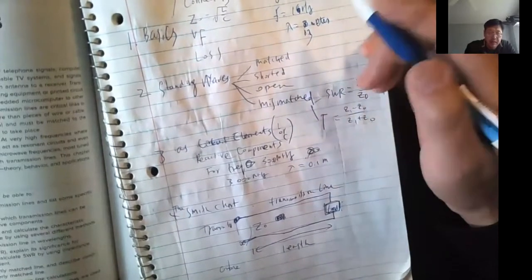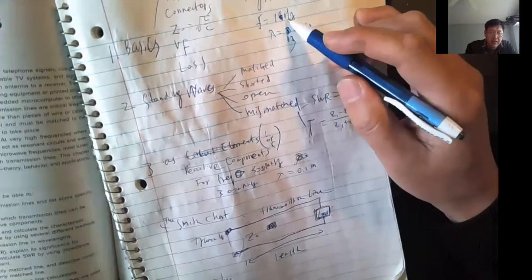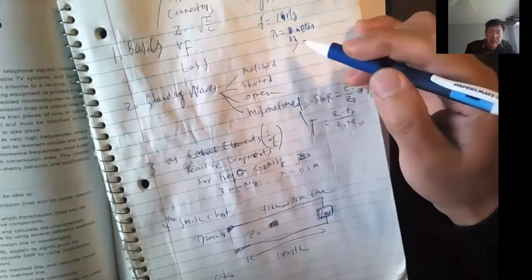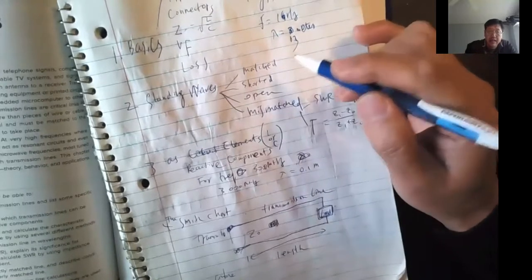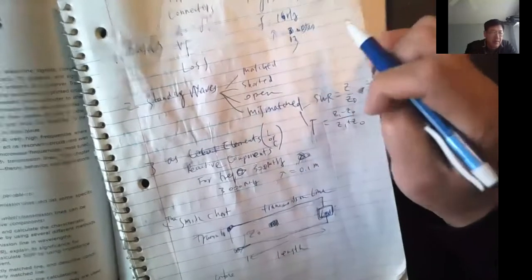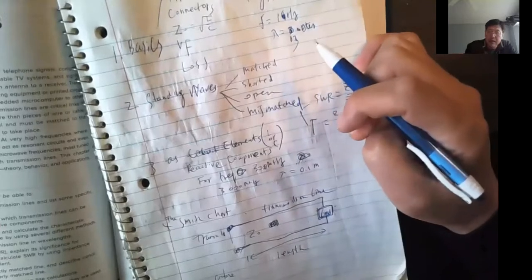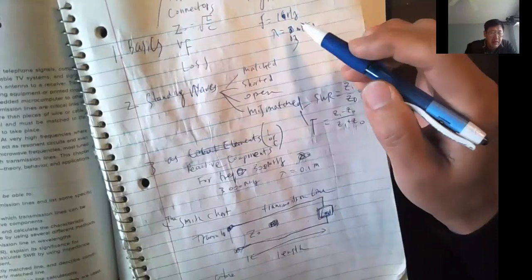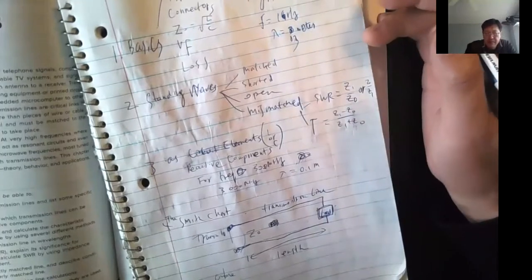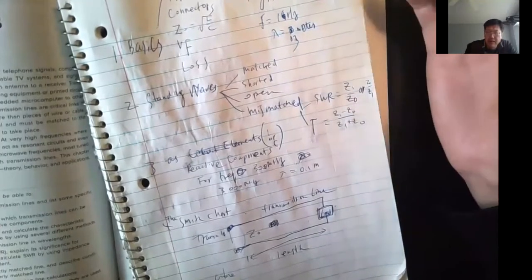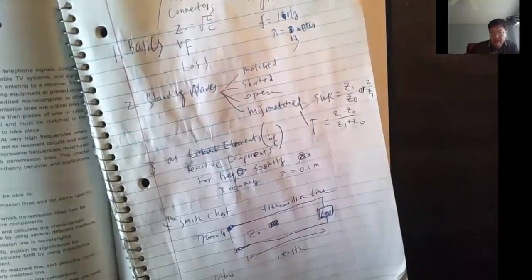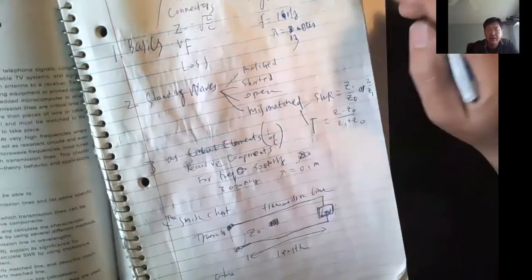That's what's unique about the signal at higher frequencies, because the lambda, the wavelength, is very short, and you get something unique happening. Conventionally, when we talk about signals of several thousand hertz or even megahertz, the wavelengths are miles or hundreds of miles long. So you do not usually care about this voltage distribution over several hundred miles.